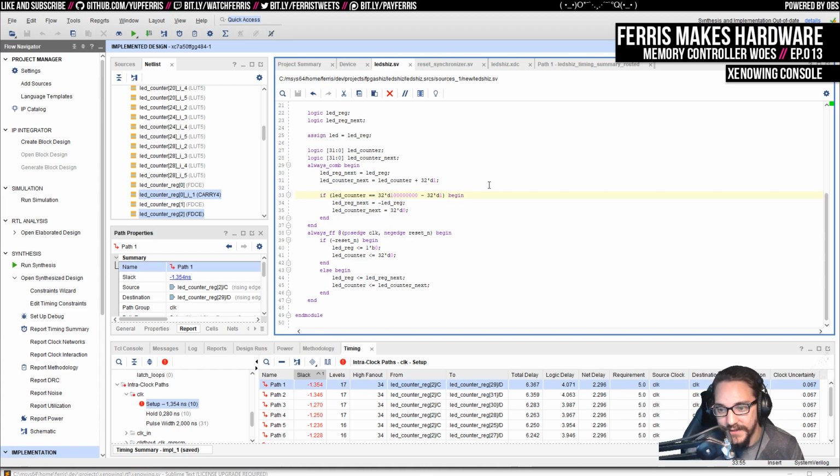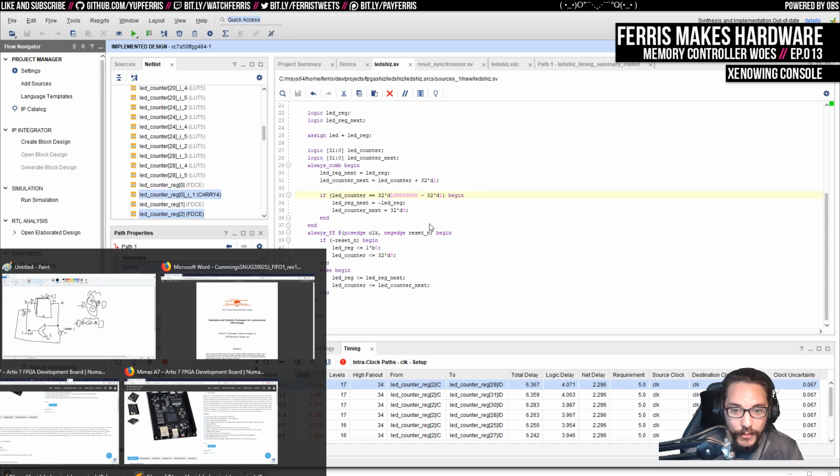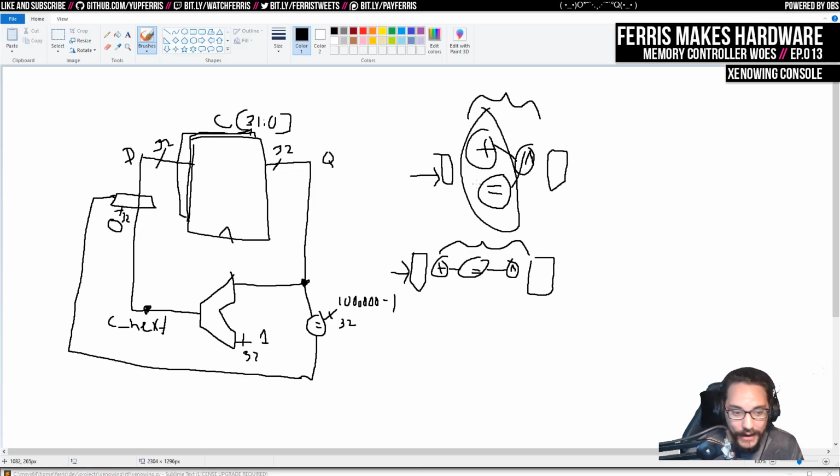But there are options. So there are other things like you can retime your design to try and fix this, because one way to fix that would be exactly how I had it before, which is just rearrange the data dependencies such that these can be in hardware executed in parallel before this one, and then it works. Another way to do this is if we don't mind if this signal were a cycle late, we could stick registers here. And then that means that now this path has an entire cycle to settle, and this path has an entire cycle to settle.